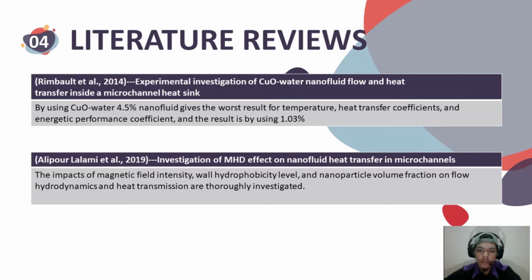an experimental investigation of CuO water nanofluid flow and heat transfer inside a microchannel heat sink. By using CuO water at 4.5% concentration, the nanofluid gives the worst result for temperature, heat transfer coefficient and energy performance coefficient, and the best result is by using 1.03 concentration.